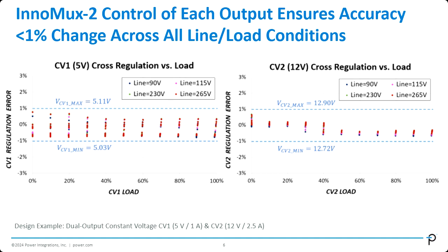But if your 5 volt power is very, very low, then there's still a chance of using single winding with 5 volts or 5 volts plus 24 volt, because you don't need that much discharging time on your 5 volts. So going a little bit slow should also be fine. So yeah, it really depends on your design's output voltage and the power allocation.